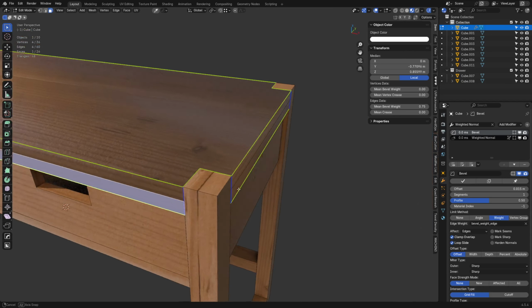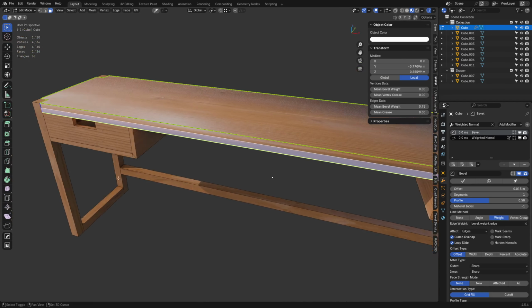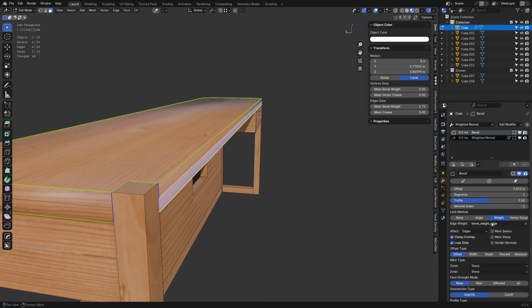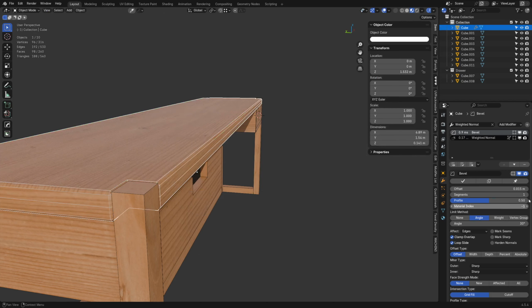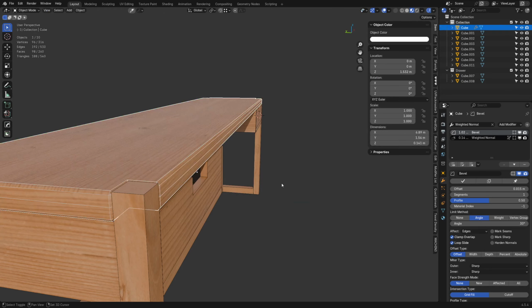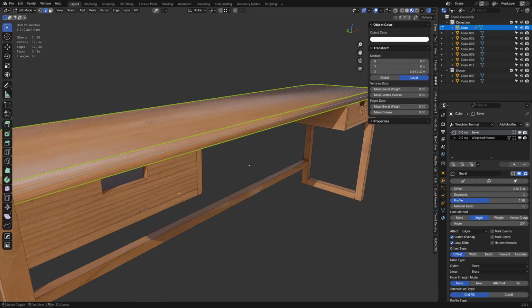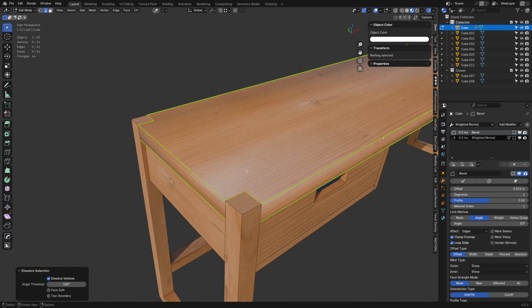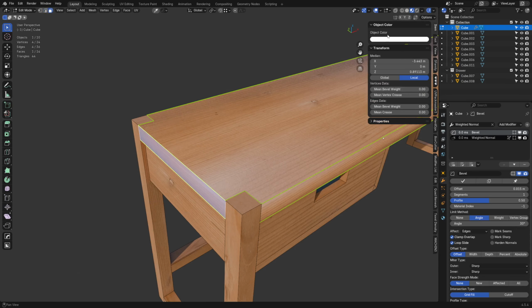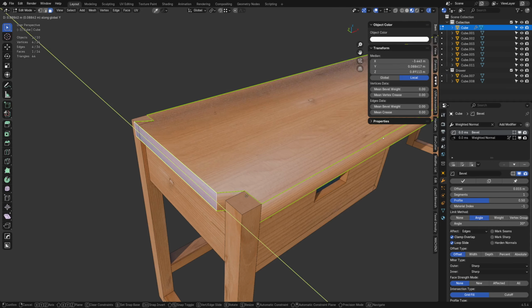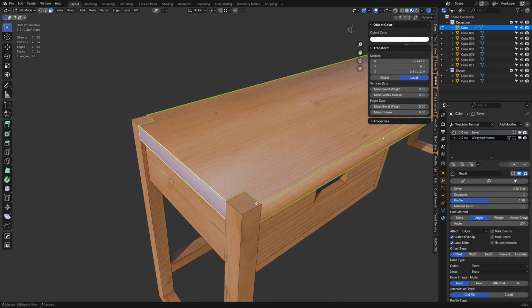I just want to point this out, although we didn't really get into it with this project. The idea is that you can do a thing called, and we're going to switch this back to angle anyways. I'm not going to use the bevel weights like that. We're going to actually remove them too, so we don't need them. We can shift things around while preserving the UVs. So a lot of times, if you move an edge or a face or whatever the case, start moving it around, you see it distorts things, right?